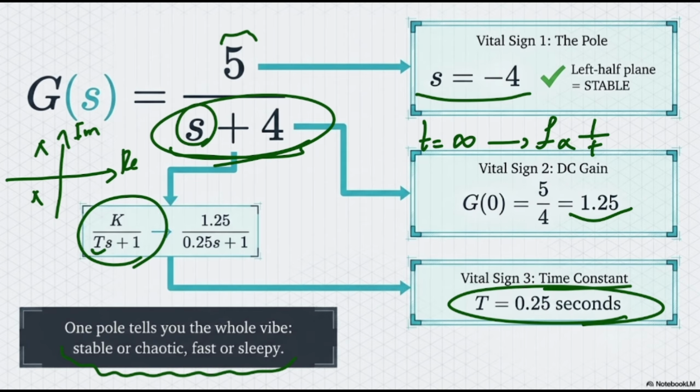By the way, if you would like to see how fast our system is, or at least compare two systems by their speed, we can see how big their poles are, considering that both of them have their poles on the left side of the S-plane, or LHS. It means that whichever system has poles that are farther from the origin has more speed than the other one.